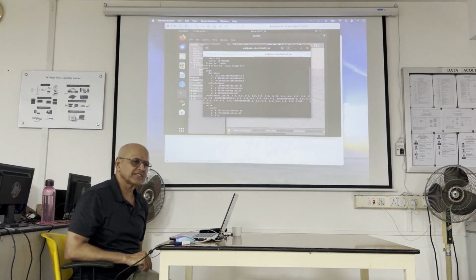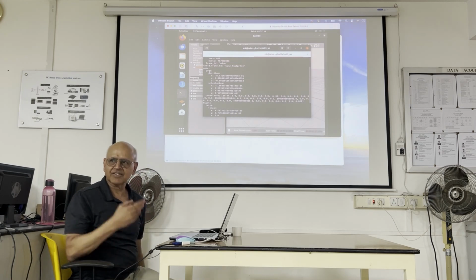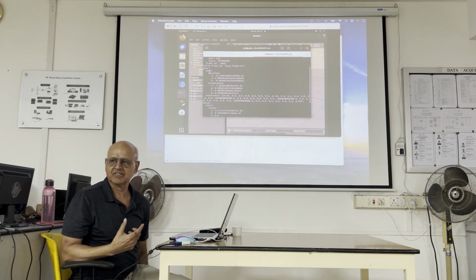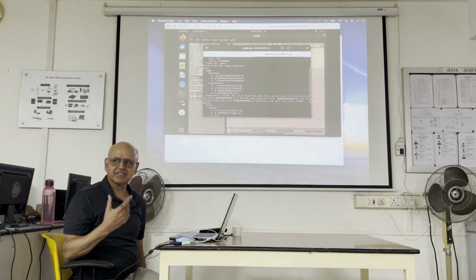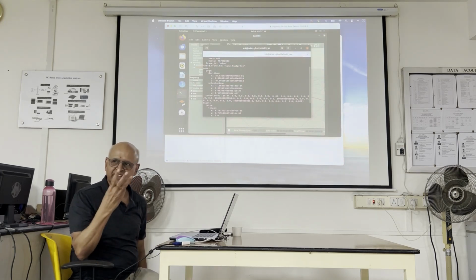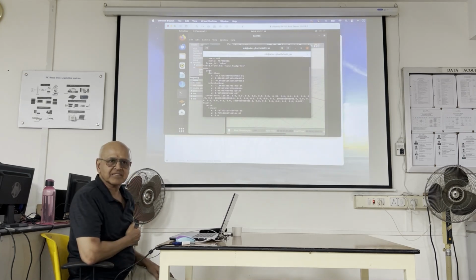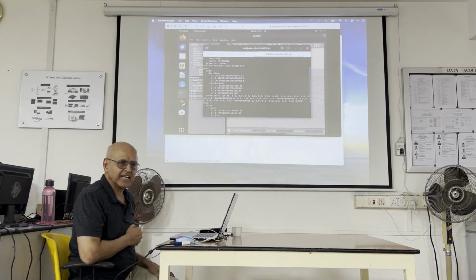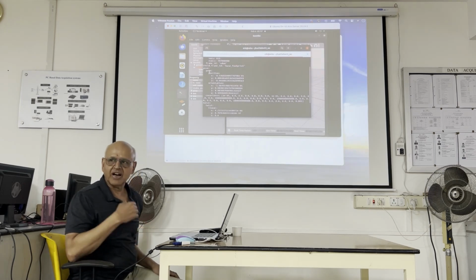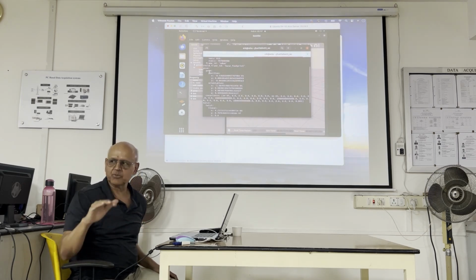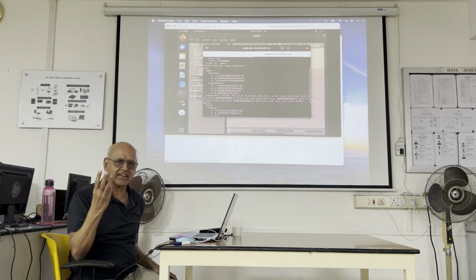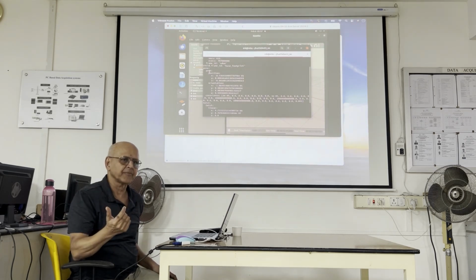So pose is the name used in robotics for the localization information. Essentially it gives you the 3 numbers, but we see more than 3 numbers here. We see 7 numbers. And it's divided into position and orientation. Now, I told you that when the robot is moving in a flat plane, only X and Y are needed, Z is not needed.